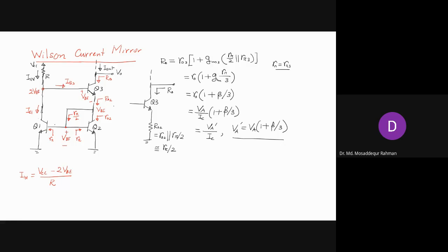The other base currents, the IB and IB here, will be coming from here; part of this is coming from I out. So I out has to share some of the burden of this extra base current, and part is shared by I in.